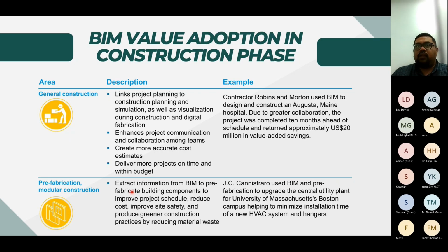Then for every panel, we also mark up where the location of the switch socket outlet is, where the trunking is, where the conduit is laid, something like that. So all these elements we model. So when the IBS manufacturer manufactures their panel, they will install everything in advance inside the room. Okay.